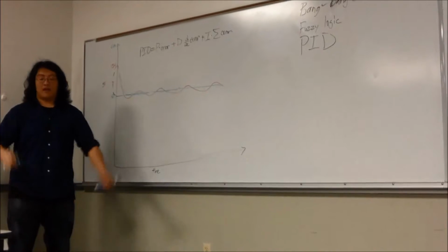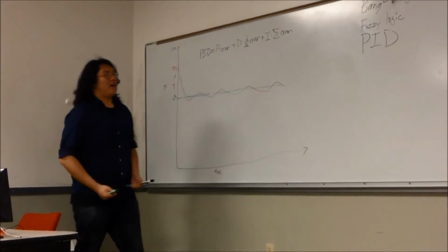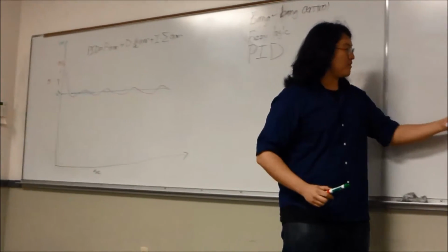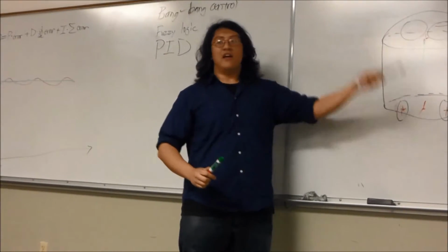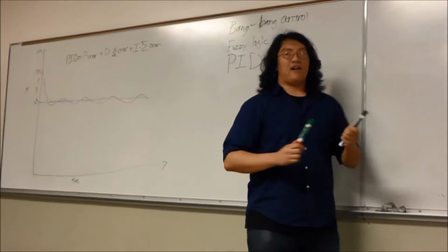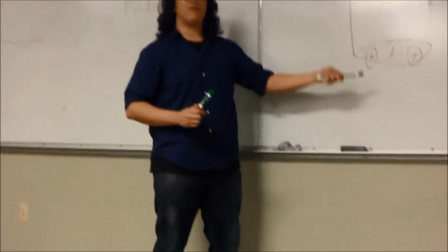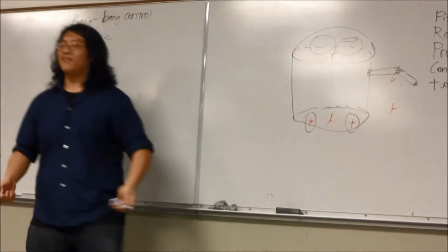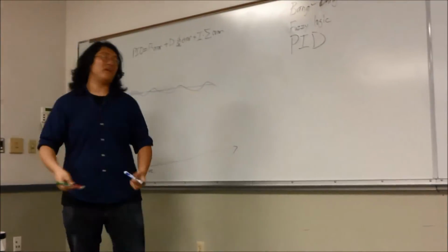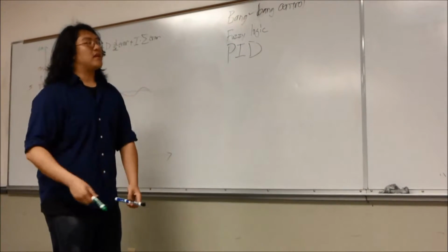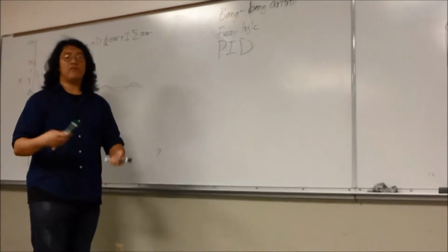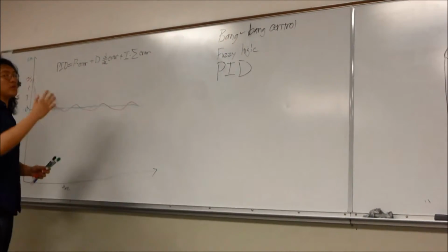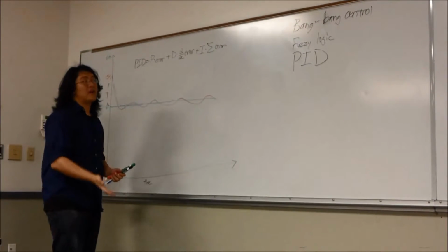Model-based control basically says, I know what my robot is. I know the mass of R2-D2, I know the diameter of the wheels, I know the friction between the contact surfaces, I know everything, and I know physics. I can solve exactly what motor power I need to output to my motors to do exactly what I want it to do, theoretically. It doesn't work perfectly in real life, but many people have gotten very close to basically ideal control of your machine because you know so much about it and the world that it's interacting with.